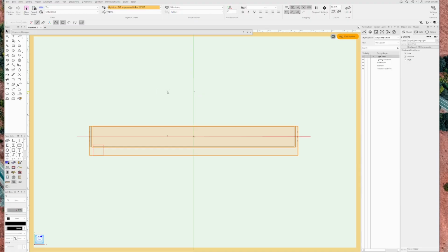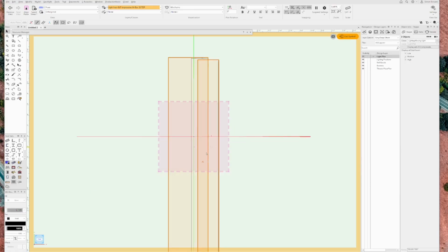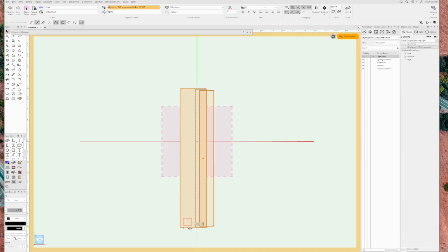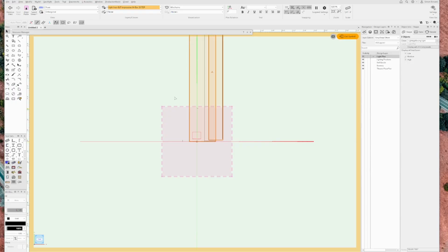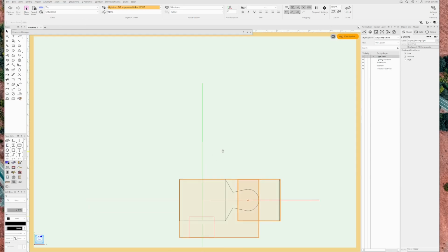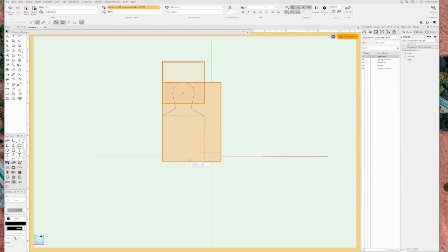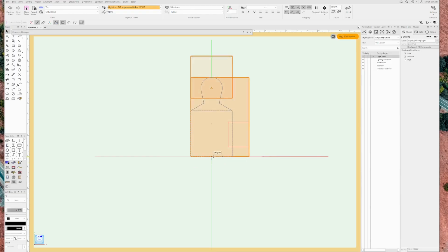So to make sure it's properly oriented, let's go to front view, Control L the thing. And in this specific case, I need the insertion point to be the bottom of the fixture when we install it vertically. So I'm going to set this to the 0 and then look at it from the top now to make sure that I align it properly, which was that bottom on the bottom and the connector is on the right. So I'm just going to rotate this in this direction and then take the bottom and match it right here.